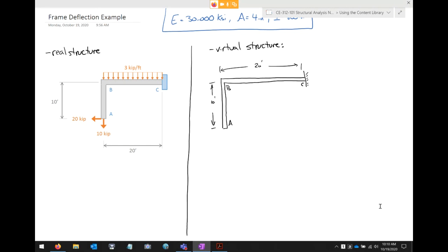I'm assuming we'll be moving the coordinate axes, but you also went over the sign convention for positive shear forces and positive bending moments: when you make a cut and look to the left, positive shear is down, and when you look to the right, positive shear is up, and same for positive bending moments. So is that the same?